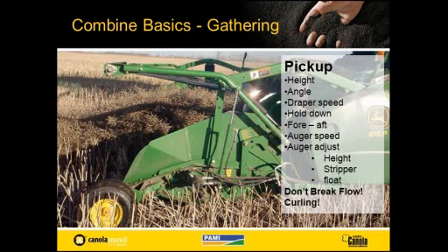The angle is important, because we don't want to pull the swath apart. So if you have your pickup speed a little fast and very flat, you might see it breaking ahead of the pickup. If you lift that pickup a little bit and slow the speed down, you might see it come up very nicely and feed into the auger. If you're going a little on the slow side with the pickup, you may see the auger pulling it away, and again, that's introducing a break in the swath, and it's going to start slug feeding your machine.